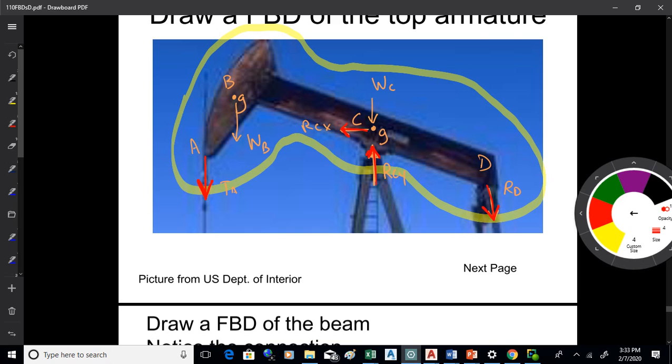You might have some variations on what I've got, especially in how you handle the weights. But the thing I would like to make sure you're getting is that's a cable that pulls. That's a linkage, so the force in the linkage follows the direction of the linkage. It goes from one link to the other. That's how the force goes. And then this is a pin joint because the object rocks around the pin joint.